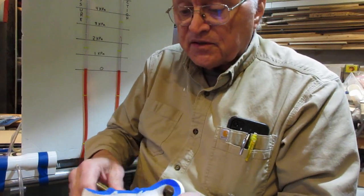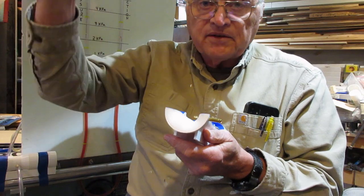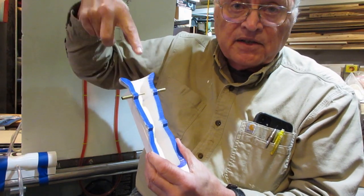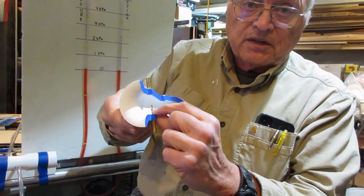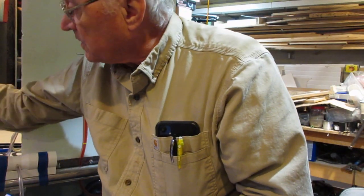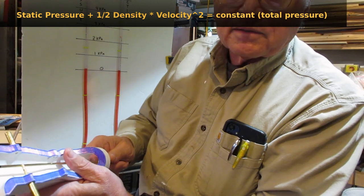Now, what we expect is we have ambient pressure out here, right? It has a total pressure. The air's not moving, okay? We have a total pressure equal to atmospheric pressure, okay? And as it comes in, the streamline coming in, this streamline should maintain the same total pressure as the atmosphere. So our pitot tube here should measure the same pressure, and the same pressure here in the pitot tube, or if we're using the pitot probe, there shouldn't be much change in the total pressure or pitot pressure as we come back, okay?